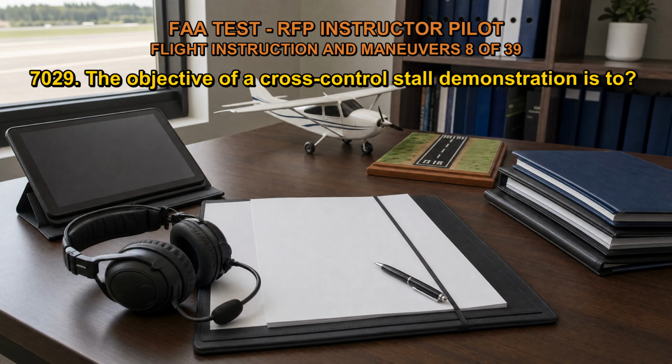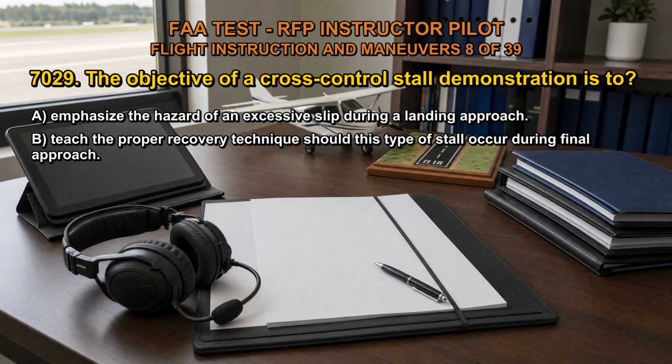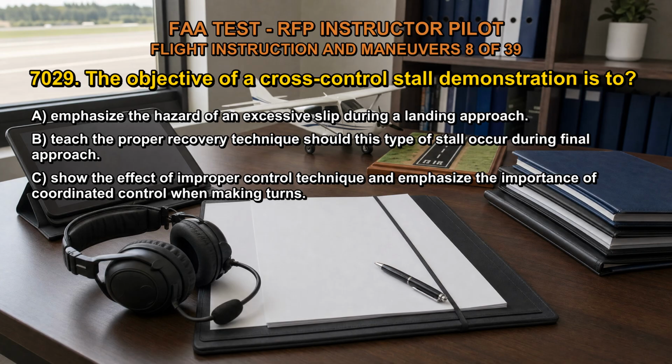7029. The objective of a cross-control stall demonstration is to A. Emphasize the hazard of an excessive slip during a landing approach. B. Teach the proper recovery technique should this type of stall occur during final approach. C. Show the effect of improper control technique and emphasize the importance of coordinated control when making turns. The correct answer is C.